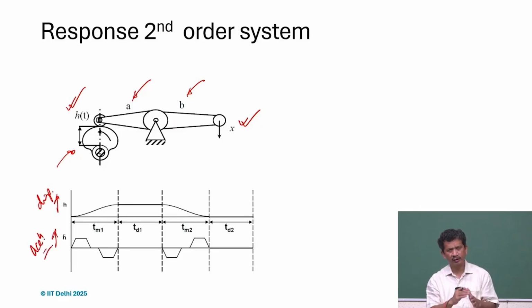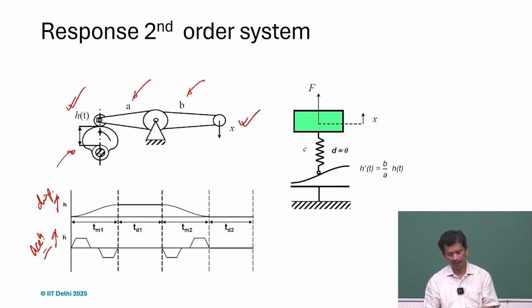We can see that even though the displacement curve can be very smooth, in cam design, when we talk about kinematics, we realize that the acceleration can be very different. It can have a very big amplitude and many times be discontinuous, and that can give rise to a lot of issues. So we'll look at it when we compare and try to model it.